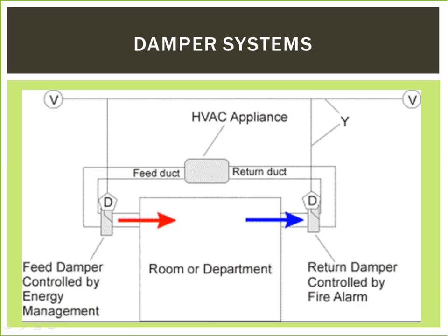Fire dampers are fitted where the ductwork passes through a fire compartment wall or fire curtain as part of a fire control strategy. Fire dampers can be controlled by the fire alarm system. However, in many circumstances, these dampers are held open by means of fusible links. When subjected to heat, these links fracture and allow the damper to close under the influence of the integral closing spring. The links are attached to the damper such that the dampers can be released manually for testing purposes.